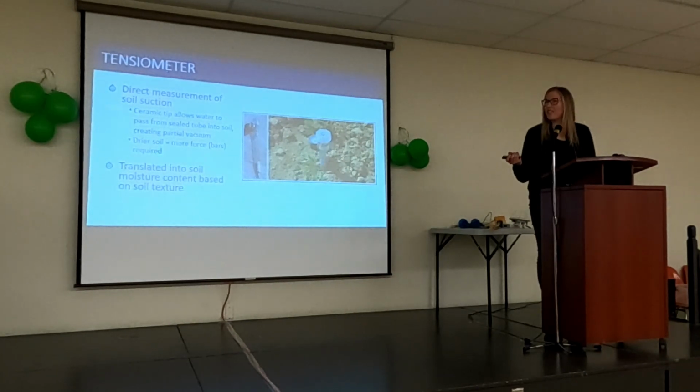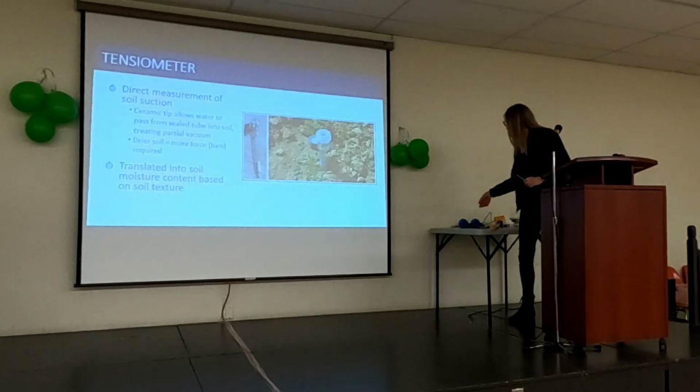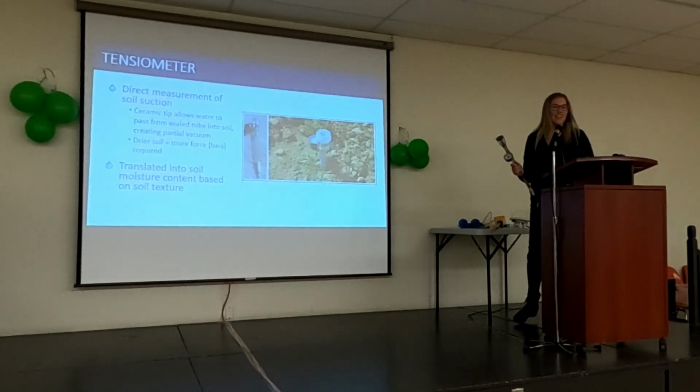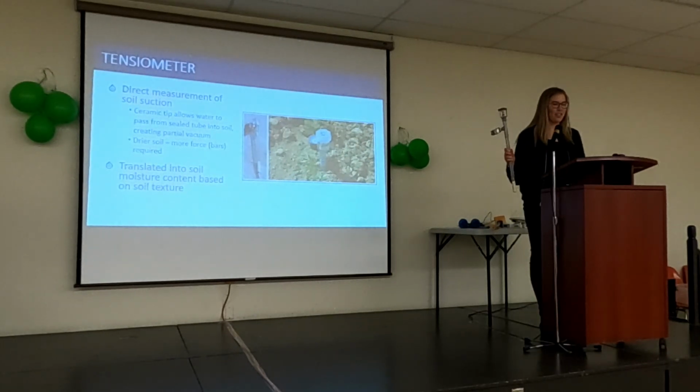So now I'm going to move on to some of the sensors that are available. I've never actually used a tensiometer before, but I'll just grab it here. So this instrument actually measures the soil suction or the soil tension, I guess. And then that tension can be translated into moisture content based on the texture.